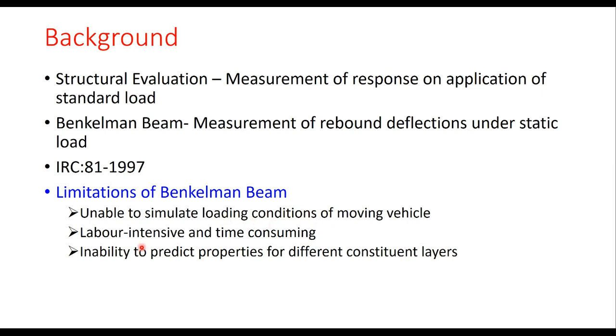The procedure is labor intensive and very slow, and it does not have the ability to predict properties for different constituent layers. So in Benkelman beam, what we get is the response of the entire pavement, and this response is related to the requirement of overlay.